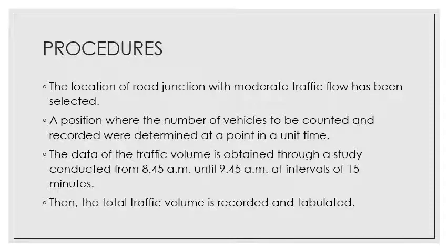You have to determine the position where the number of vehicles will be counted and recorded at a point of time. If we conduct for 1 hour, you have to do it at intervals of, for example, 15 minutes, so that you see the pattern.